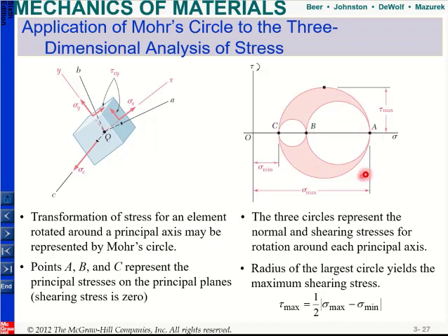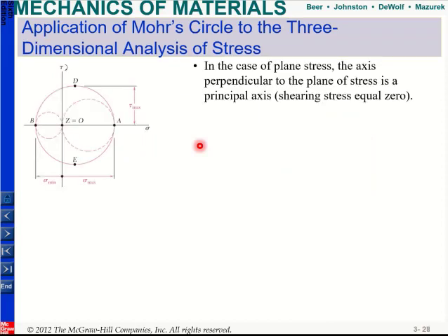But if you are looking at the absolute maximum, you need to find your 3 principal stresses, determine which one is maximum and which one is minimum, and use this equation. We are not going to deal with 3D stresses, but we need to apply this knowledge to our plane stress. And actually, before we do that, let's look at a general case again.